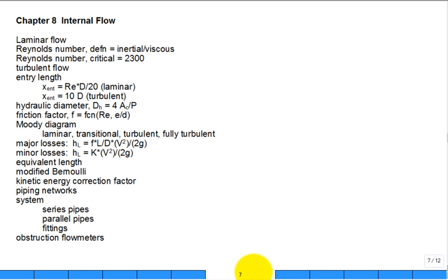Internal flow. Idea, we've really emphasized laminar flow, internal into a pipe. If it's fully developed, what is the shape? Quadratic shape to it. Nice bullet shape or quadratic shape to it.